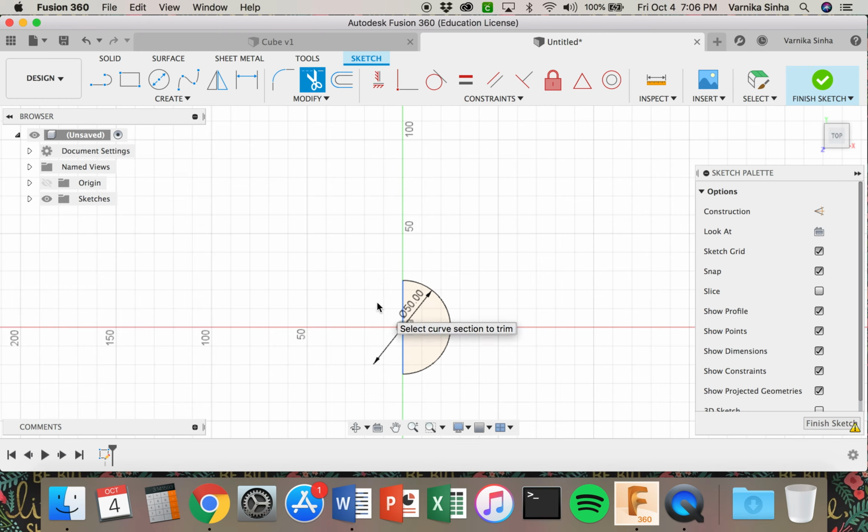So here we are, we have a semicircle, and now we can rotate this semicircle along this axis 360 degrees to make a sphere. Since this is an axis and not necessarily the length, you could have made this axis bigger. It wouldn't have made a difference because the axis isn't the thing that's going to be revolved. It's a sketch. So the dimensions of the axis can be whatever as long as it's placed correctly. It's the sketch that needs to have the correct dimensions.